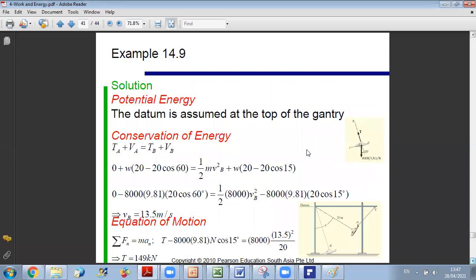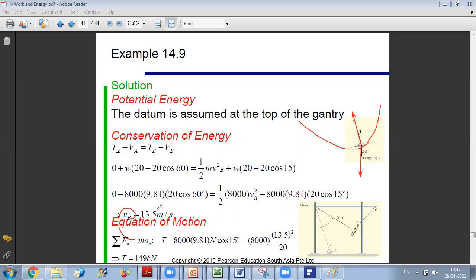If we go back to the free body diagram, what are the forces acting on the airplane? We said the weight with the tension. Okay? Now, because we have circular motion, I told you right away, whenever there is circular motion, think of UT UN directly, because if we know VB we can get AN, and we already calculated the velocity. Now, because we don't know where the maximum tension is, we should do the analysis at any angle theta, and we will prove together that the highest tension will be at B.